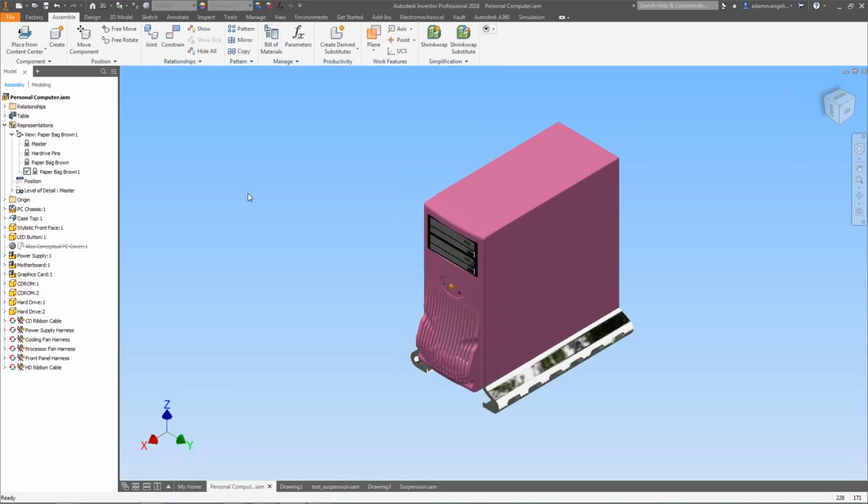So he changed it in a locked state from brown to pink, but the second he clicked on another view or he reset the view, it defaulted back to brown because that's the save state that actual view was in. So note that you can make certain changes when you've got a locked view, but they do not save down. So I'm going to make one more color just because it's a nice little workflow. This is going to be a really common workflow for all of these representations, essentially. You can just right-click, copy it down, activate the one that you need to, and then make your changes appropriately.